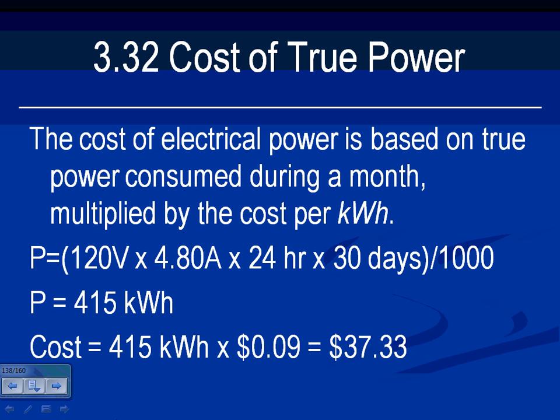Paying per watt, guys, is a smaller amount. So they do it per every 1 kilowatt will charge you 7 cents. Okay, so divide by 1,000, and then here's the kilowatt hour that you consume. What's the price that we're paying for? 9 cents. And that's how much it's going to cost you to run this piece of equipment for this amount of time. Any question, guys, about finding the price?